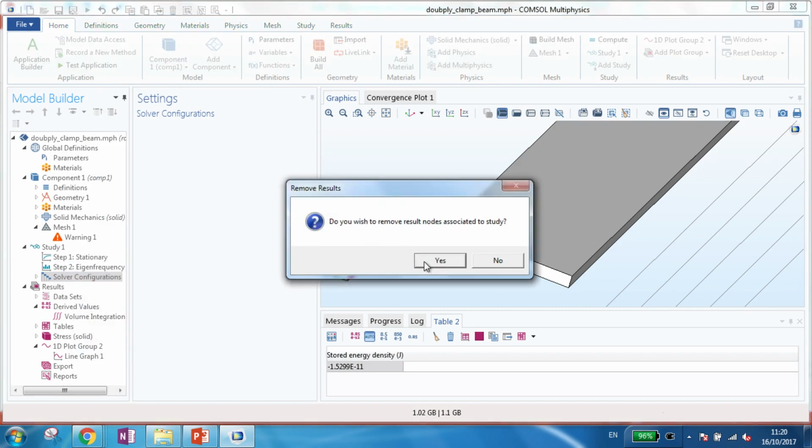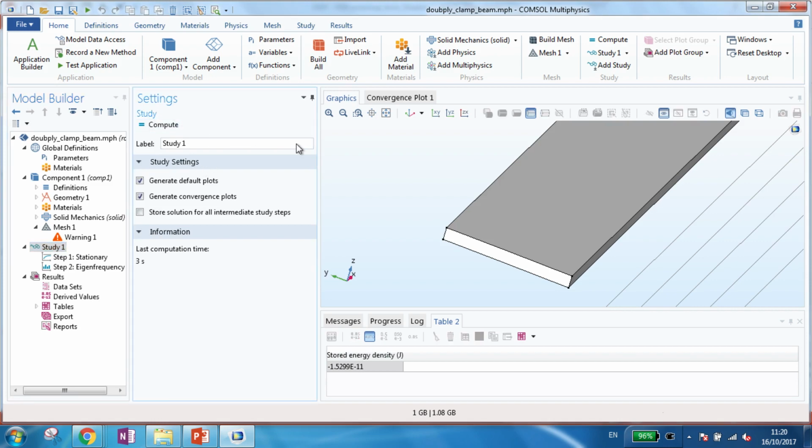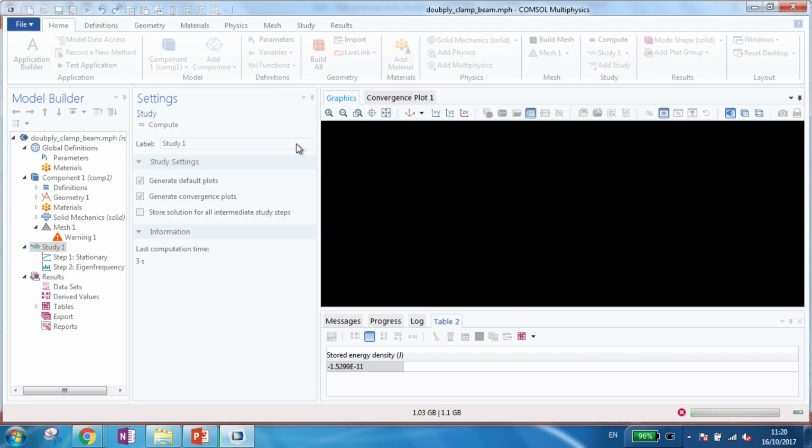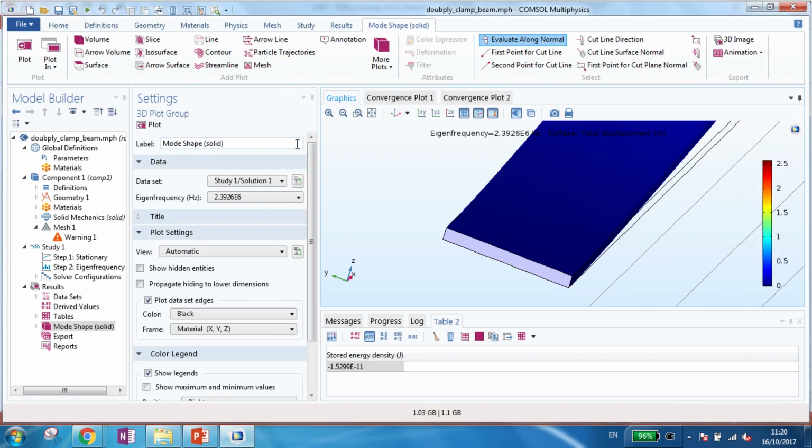And the last thing I want to tell you: there was a question on how we calculate the losses. And losses, we know the Q, the dilution factor, I mean, this is a topic of its own. You can calculate the losses if you know the intrinsic non-stressed Q, times this so-called stress dilution factor. And this stress dilution factor is the ratio of the energy stored in the elongation, or kinetic energy, divided by the energy stored only in the strain.